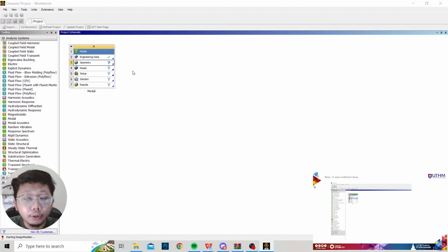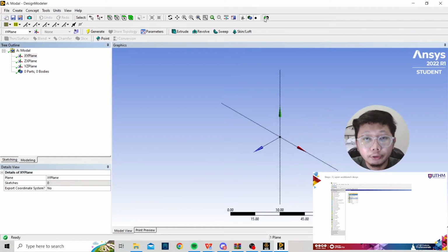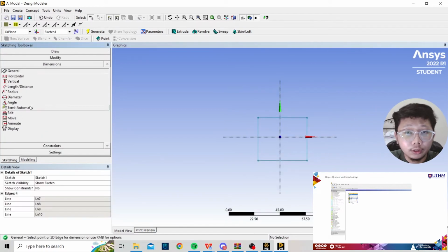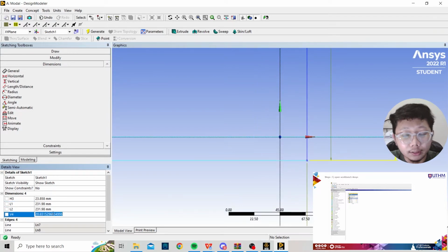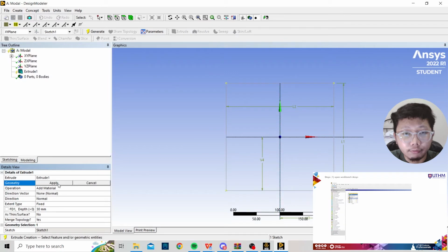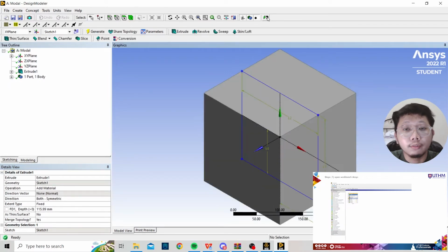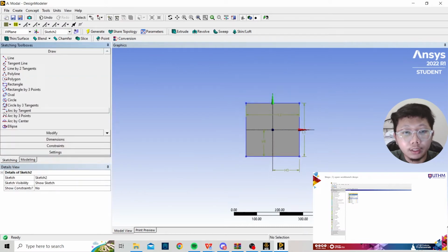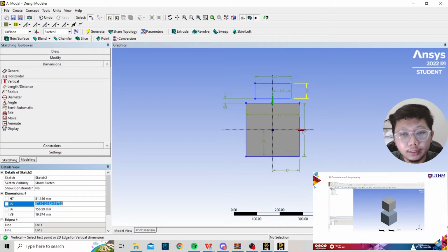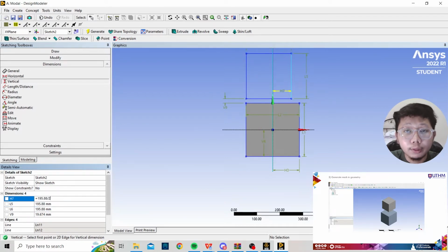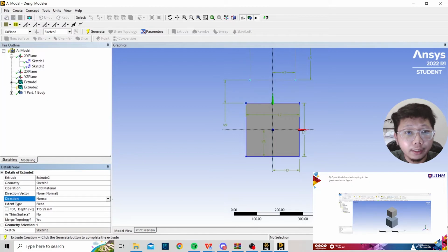Next, I'm going to explain how we are going to get the data from this Ansys. First, you have to open Workbench Ansys, and then we are going to go to engineering data. In this engineering data, we can set the density of the material that we use, which is structural steel, which is just the default of Ansys. Then after we set the engineering data, we can go to geometry. From this geometry, we are going to generate mesh. So this is the mesh that we are going to use. From this mesh, we are going to open it in model.